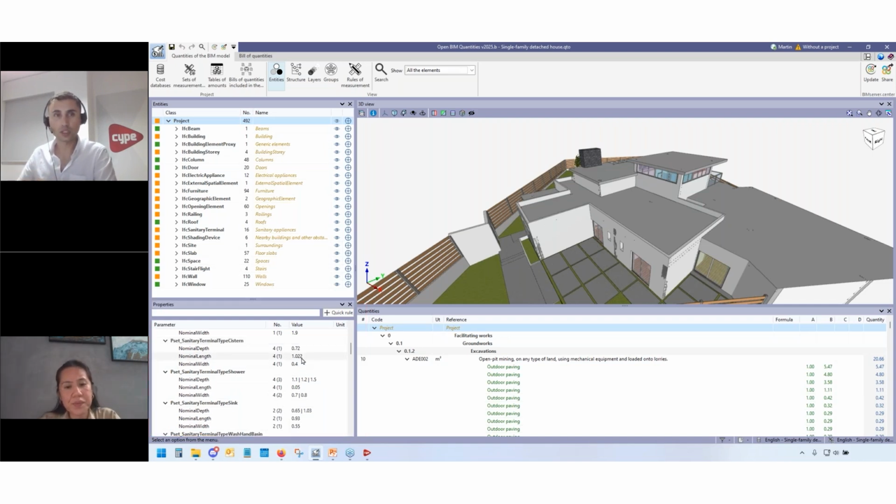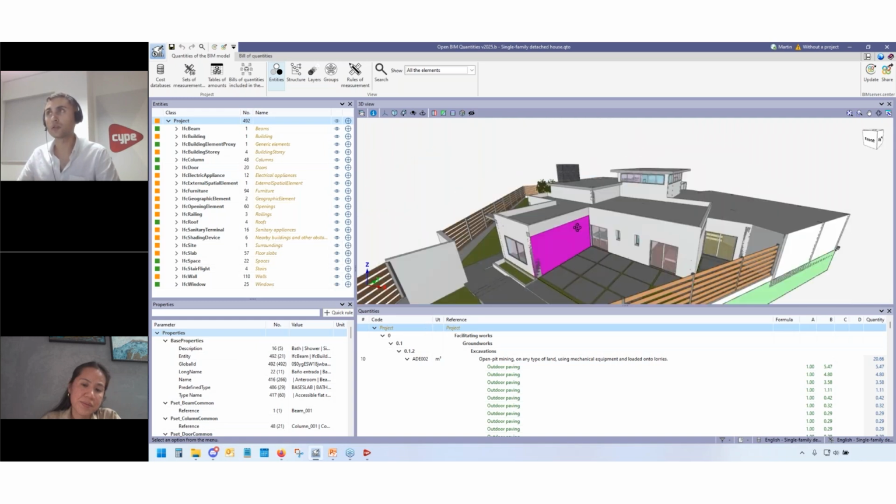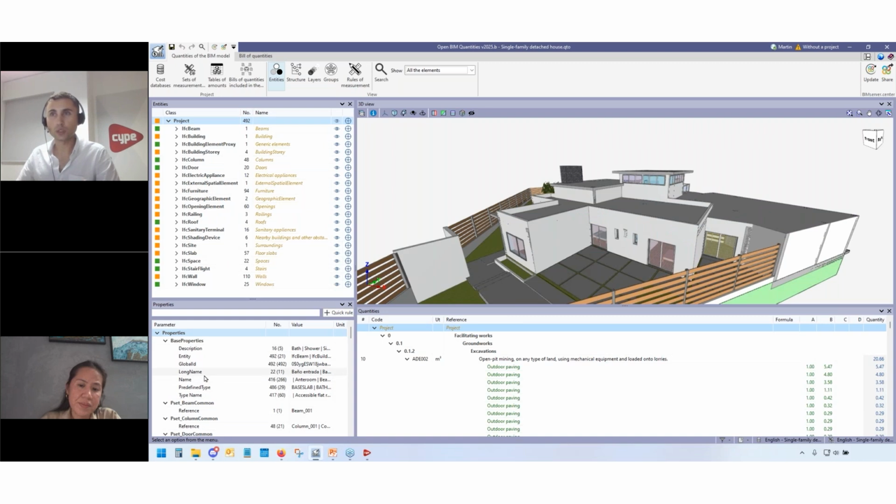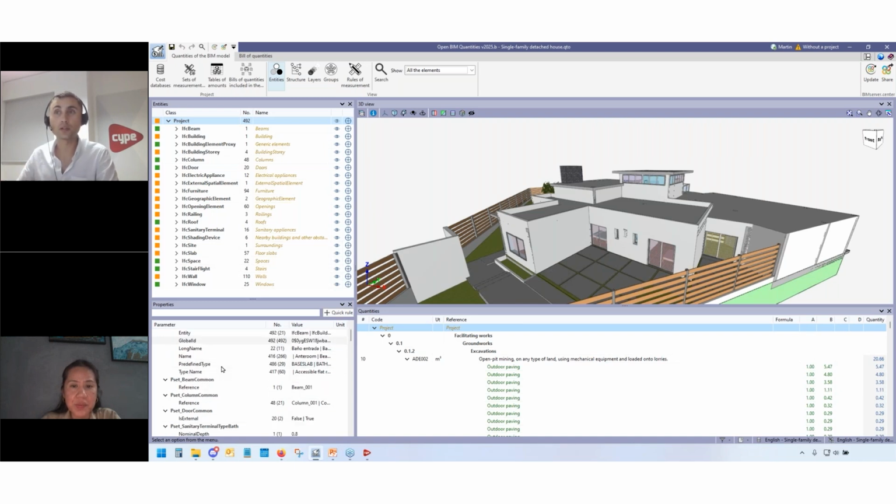The example I showed about the walls is a good example for this sort of issue. As we see in this model specifically, the modeler, the person that generated this geometry and the information present in the model, put tags and names, and structured information in an interesting and useful way, but we don't know if that's going to happen. So if we get messy information from the model with no names or just undefined elements, we may rely on the quantities. And if we know about construction in the industry, we may know that the exterior walls are thicker than the interior ones. So using that knowledge of the industry, we may get more productivity out of models that are maybe not that good.